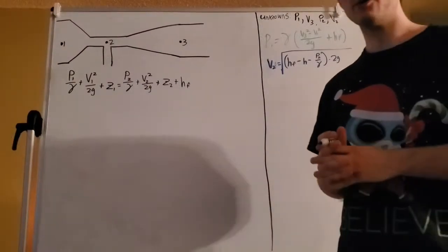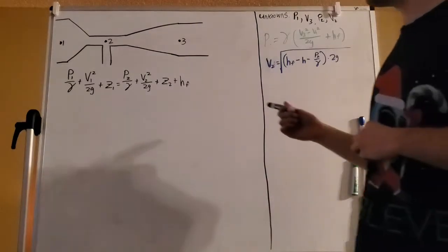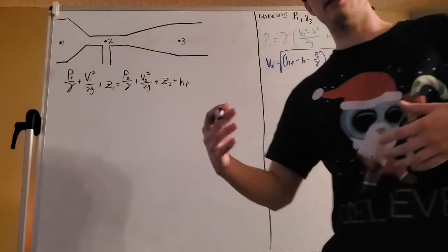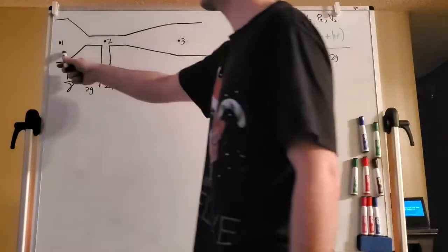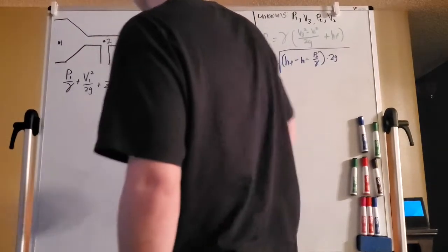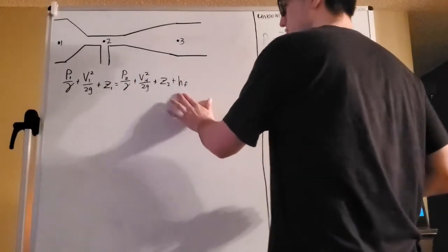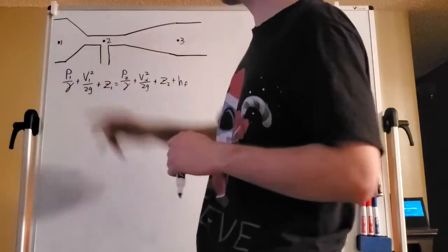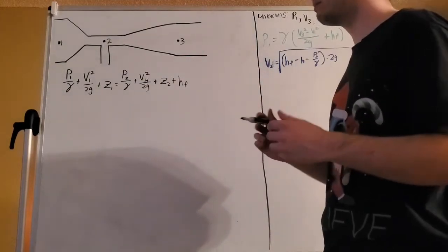All right, I will now be showing you how we got our third equation to solve our system of equations to find the ratio of the flow rates exiting the Venturi. Like the first two, we start with our Bernoulli equation, and we apply it between points 1 and 2. Likewise, we are taking into account head loss this time. When we apply the Bernoulli equation between 1 and 2, we need to cancel out values that are equal on both sides.